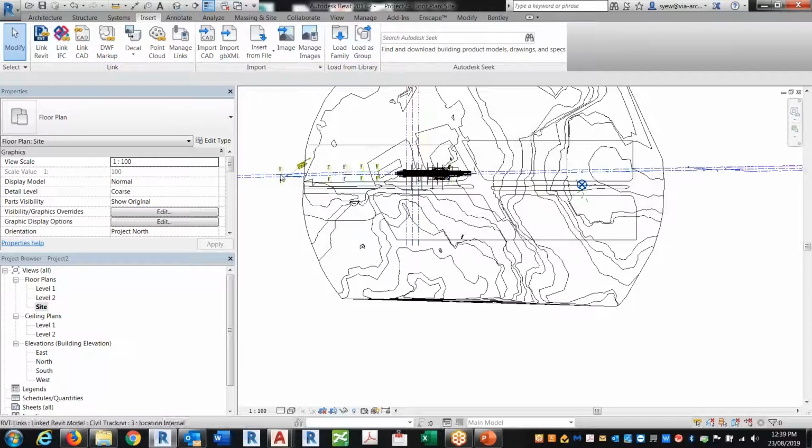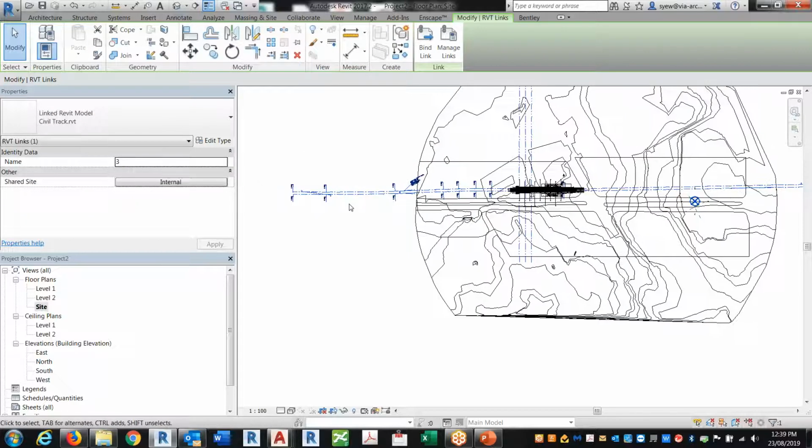The first thing I would recommend doing is that first you start out with the blank file with nothing in it, linking your CAD into that Revit file, so that that becomes the master file for all the coordinates and all the civil, where you have to share the file with the civil guys.